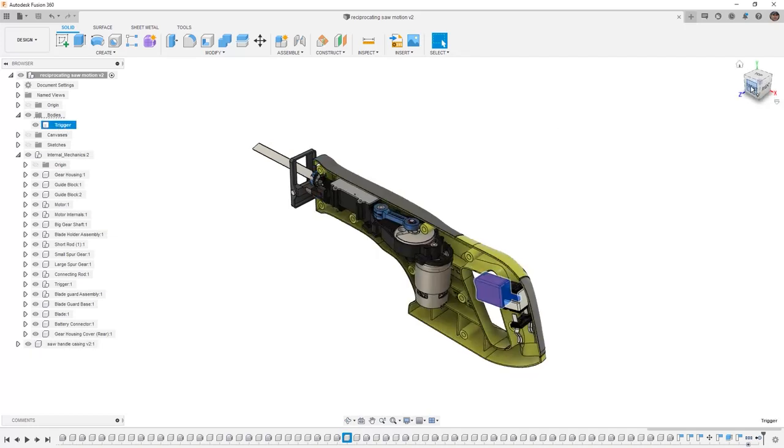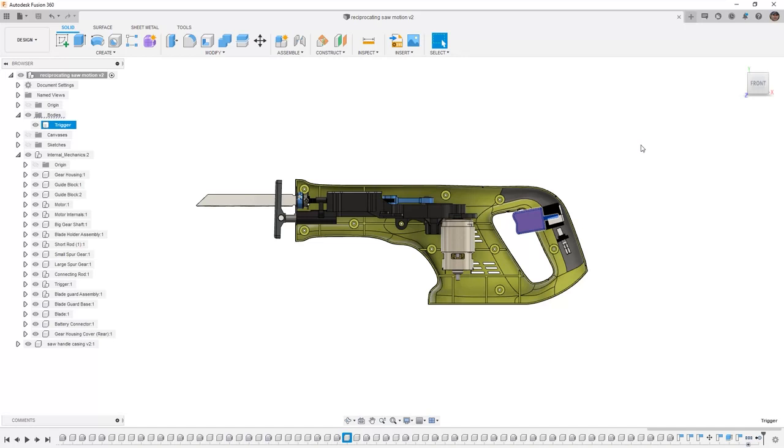Let's take a look at what makes an assembly and what we need to do when we're considering modeling with assembly techniques. The first thing to note is the difference between a body and a component. A body is based on the origin at the top level of the design. A body is fixed in space and can only be moved if you use the move, copy, or align dialogues. This means that it's not able to be a part of assembly motion.